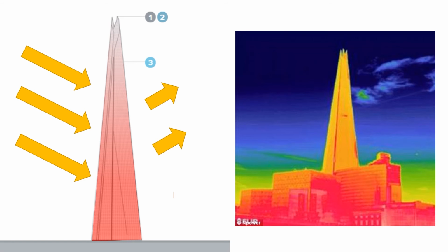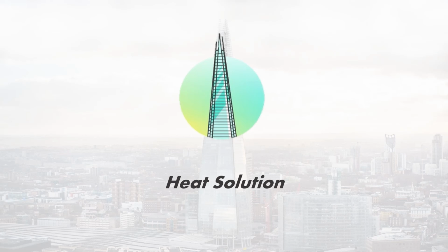Last, the skyscraper, like the shard, has a difficulty to balance temperature of the whole building. As the skyscraper has extreme height difference between the ground floor and the top, the temperature difference widens. With these factors that threaten the building's efficiency, the shard building required high-quality thermal solution. Engineers provided various solutions for building efficiency, and we'll talk about passive and active solution this week.